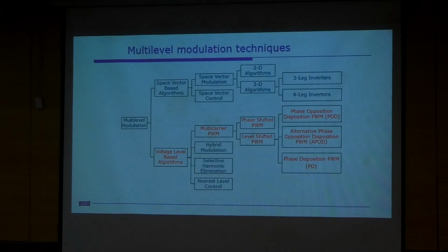Today we will discuss these commonly used carrier based techniques. One is the level shift and the other is the phase shift algorithm. First I will describe these methods. They are simple methods, and the implementation is straightforward. Next we'll see how to simulate these in MATLAB.